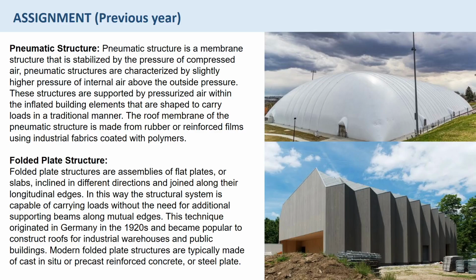A Baltimore truss has additional bracing in the lower section of the truss to prevent buckling in the compression members and to control deflection. It is mainly used for rail bridges, showing off a simple and very strong design.